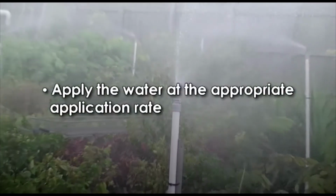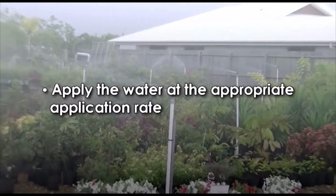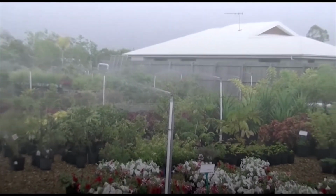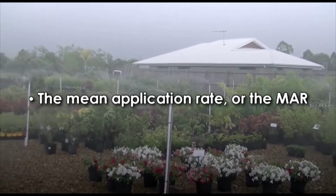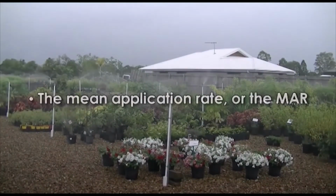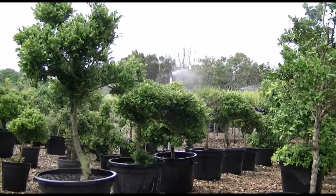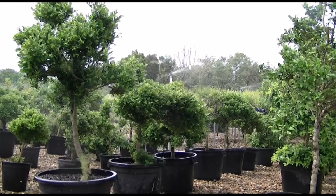An efficient overhead irrigation system should apply the water at the appropriate application rate. To take full advantage of the water holding capacity of your growing media, the mean application rate, or MAR, should be less than the absorption rate of your growing media. Application rates of between 10 mm per hour and 25 mm per hour are considered suitable depending on your growing